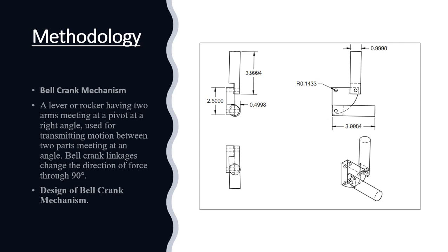We faced two main problems during the design. First, we have to fix the height at 0.76 meter, so the height should remain constant on each blow and should not exceed 0.76 meter. And the second one is the weight. When the weight reaches the required height of 0.76 meter, it will automatically be dropped. So we have used a bell crank mechanism along with a stopper chain. The bell crank mechanism was the main